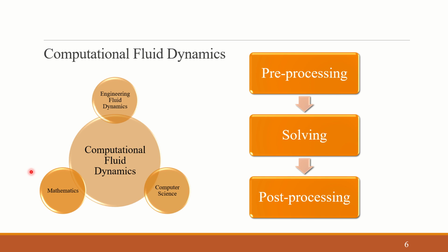If heat transfer also comes into the picture, we have additional equations like energy equations as well. And if particles or multiple phases come, it becomes a different story. For a single fluid flowing inside a system, we are talking about two equations: the mass conservation equation, that is the continuity equation, and the momentum conservation equation, the Navier-Stokes equations.